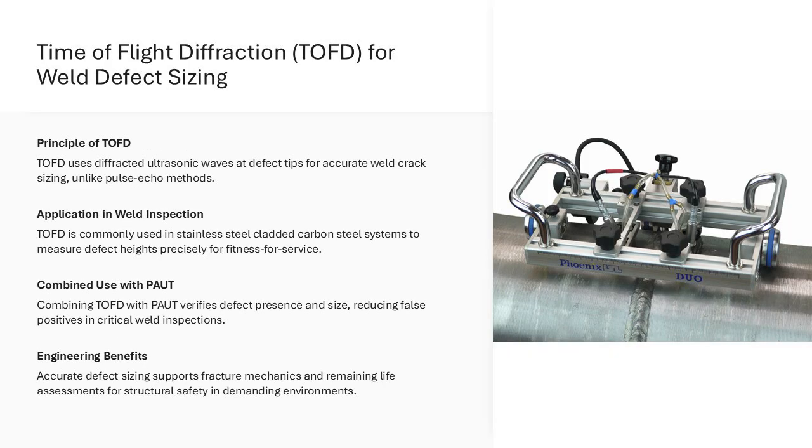Time-of-flight diffraction, TOFD, is a specialized ultrasonic technique that complements PUT, particularly for weld inspection and crack sizing. Unlike pulse-echo methods, TOFD relies on the detection of diffracted ultrasonic waves generated at the tips of defects. This makes TOFD highly accurate for through-wall sizing of cracks, regardless of their orientation.